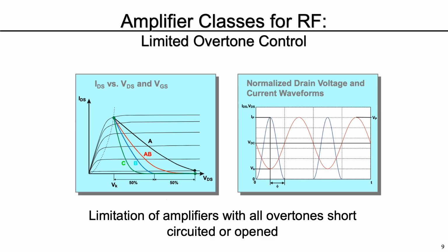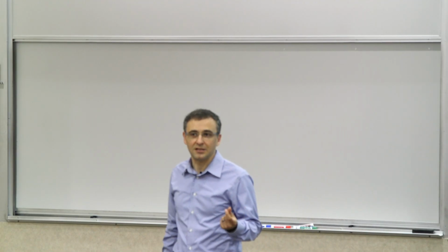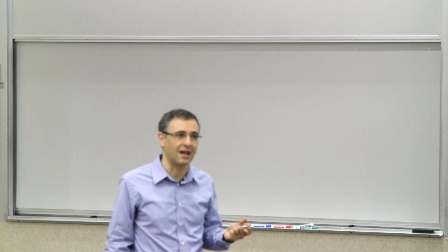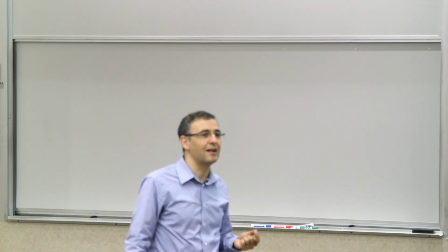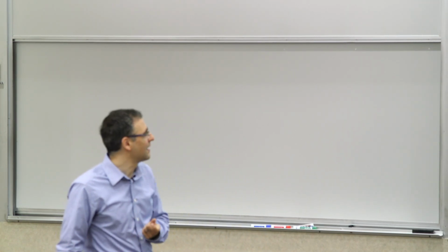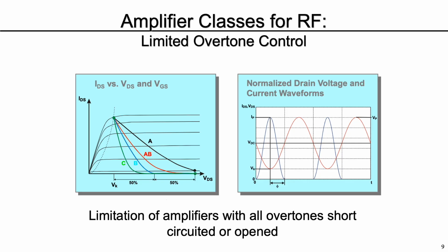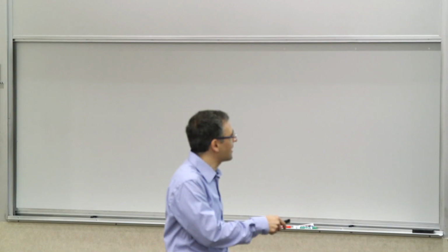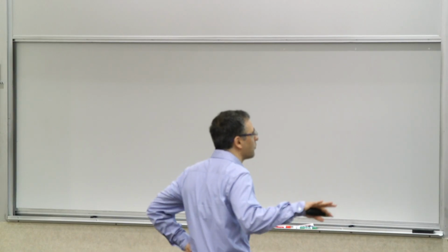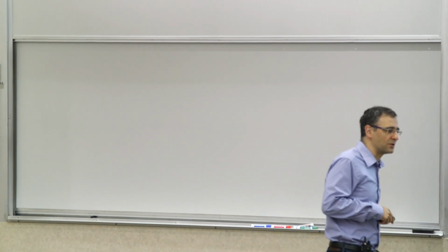And then if you go beyond that, if you make your duty cycle less than 180 degrees, or less than 50%, then you are venturing into the realm of the so-called class C, which again corresponds to an even steeper load line with a larger knee. So basically you're transitioning between the green dot on the right-hand side of that x-axis and the other green dot on the top where the knee happens. You have this transition that's less linear, and you're transitioning between those two points. That's basically your operation point moving.